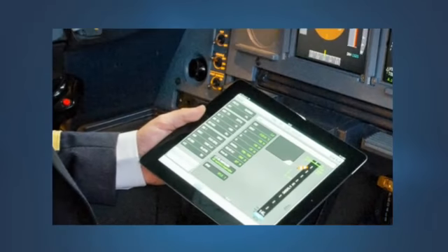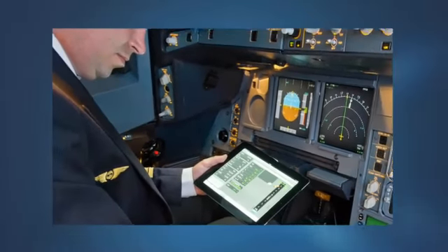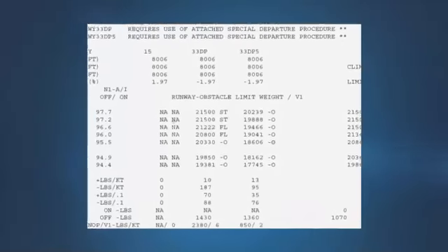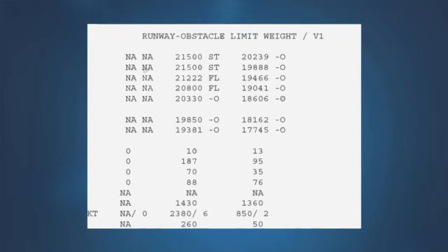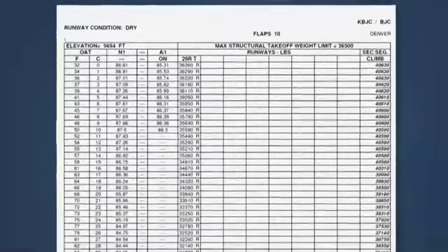Regardless of how the analysis is prepared and presented, there are a few important items that all pilots should know about the net takeoff flight path obstacle clearance analysis. The airport runway analysis prepared by the performance engineer provides the pilot with the maximum allowable takeoff weight in consideration of performance requirements for the takeoff airport and runways specified.